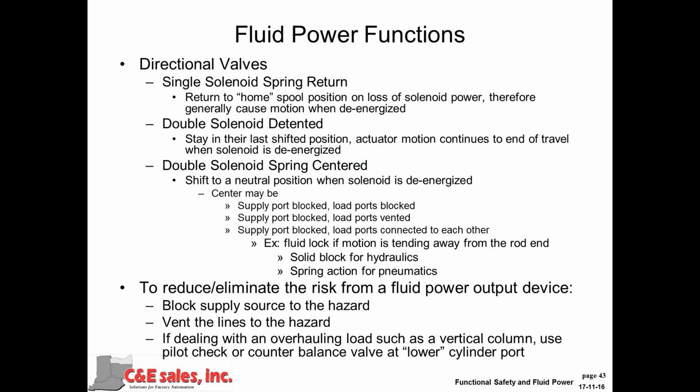In order to reduce the risk from fluid power devices, typically what we want to do is block the supply to the hazard as well as venting the lines, such as blocking the flow to the cylinder as well as blocking its exhaust.